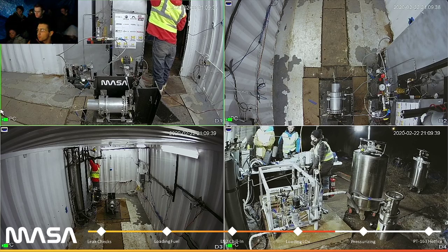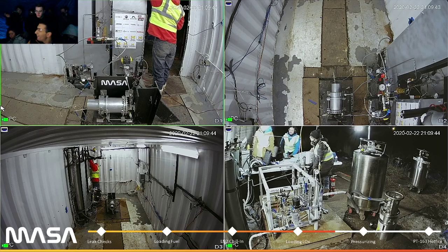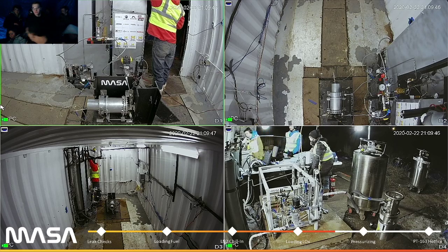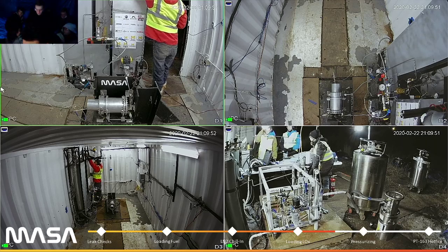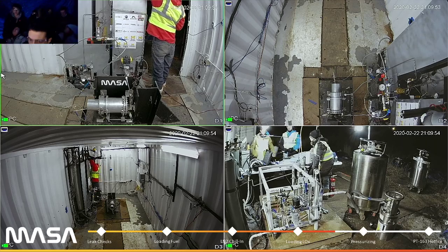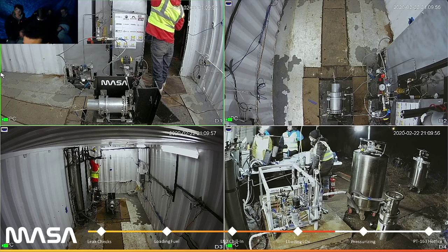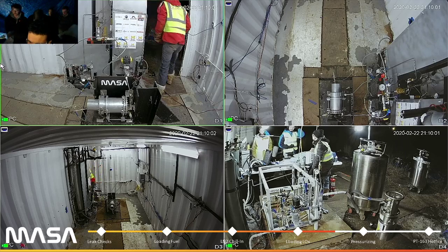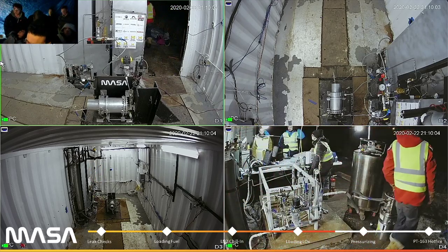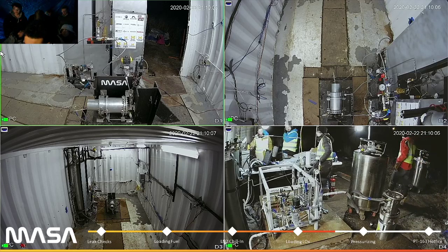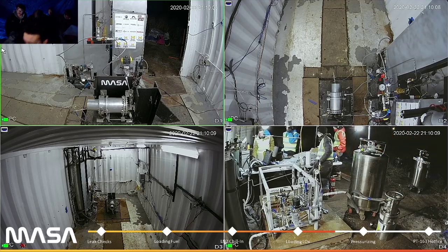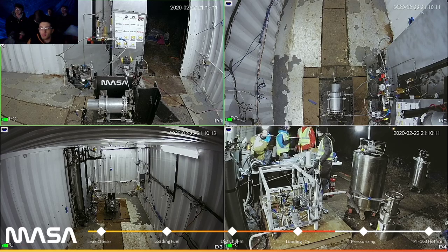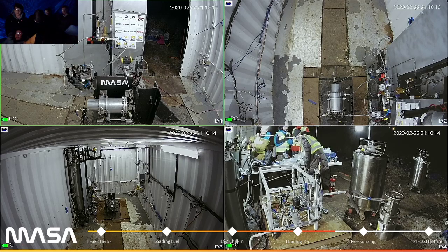We're just doing battery shenanigans. We hooked up LOX basically. Once we start filling LOX, we really can't do a lot of work behind it, so we start getting the system in the state where we're ready to do it all remotely. Right now you can see them doing some battery stuff. We're making sure that all of our batteries running the engine controller, along with our tanks, are at the right pressures and voltages to make sure that we can run the system remotely once LOX is in the system. We won't be behind the bunker while LOX is in the system, for safety reasons.